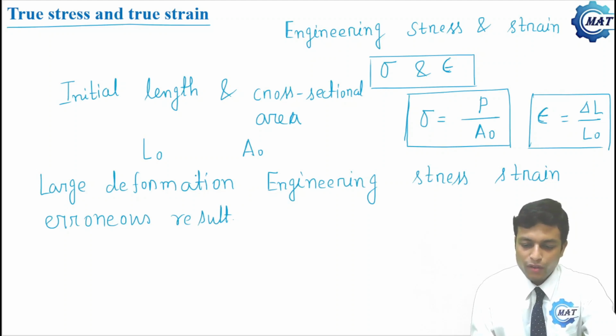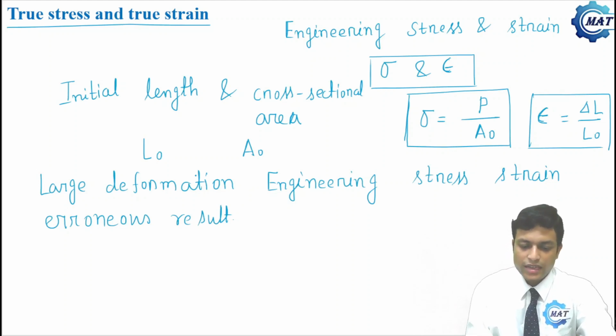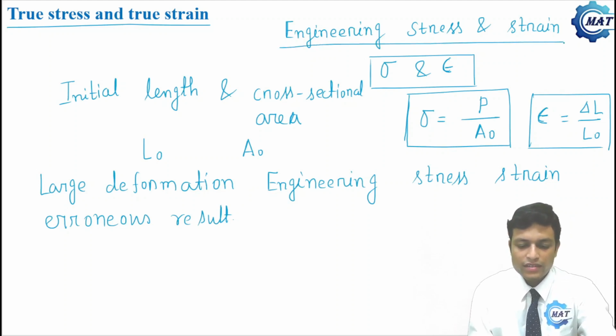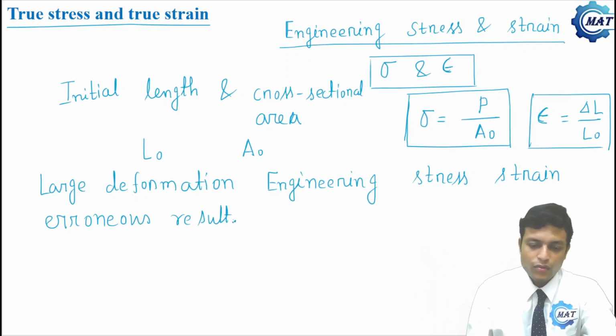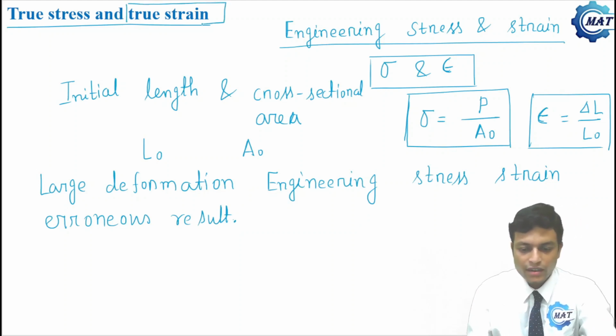For small deformation, the error is very little. Engineering stress and strain are valid for small deformation, but for large deformation we have to go for true stress and strain.